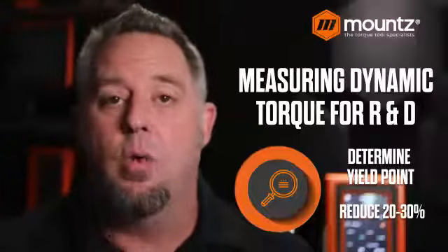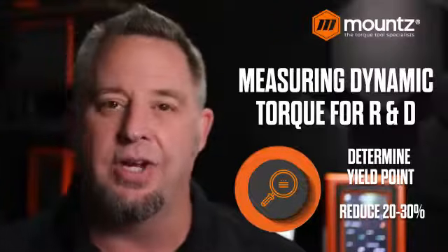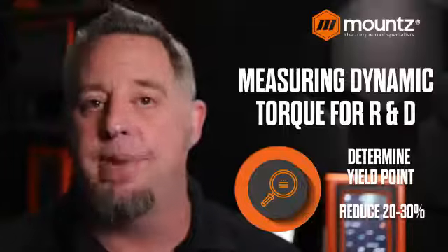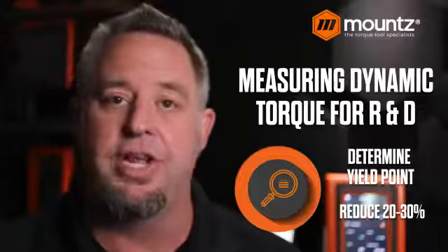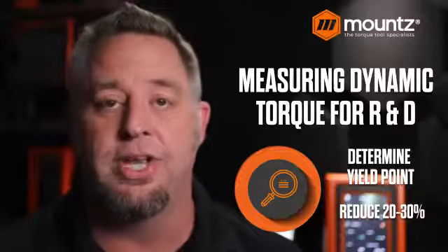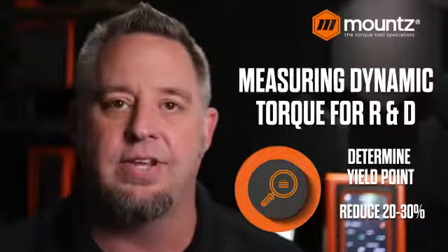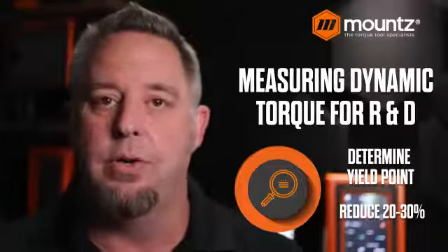And so when we find that yield point, we can then take a look at the joint characteristics, and we can back that off from that percentage of usually 20 to 30%, maybe 25%, just depends on some other factors, if there are gaskets and things like that. But that is typically where you would start.